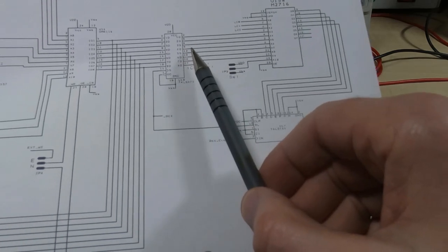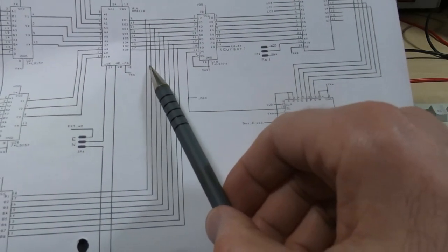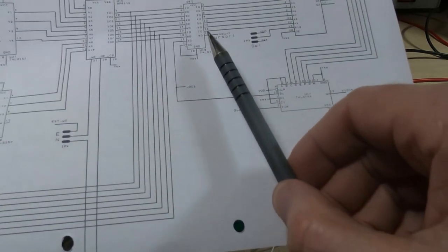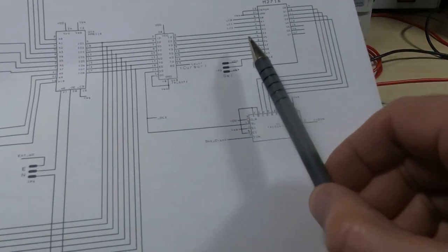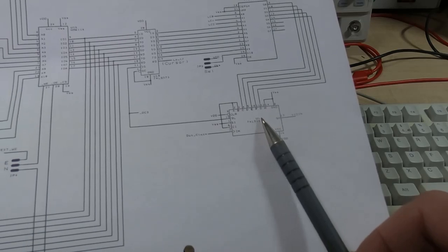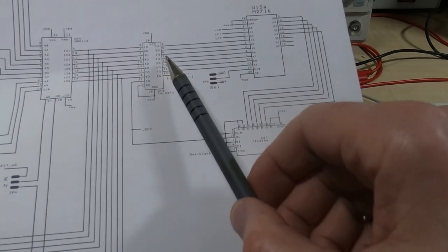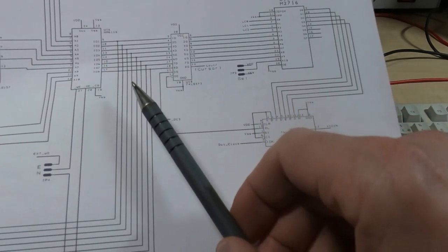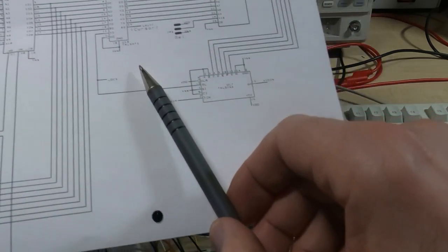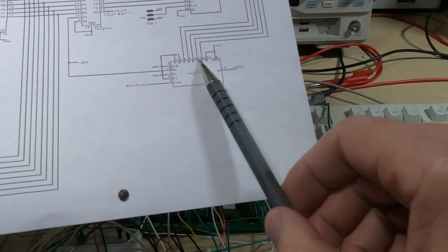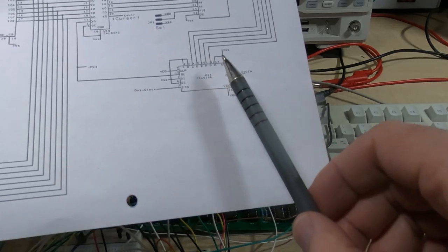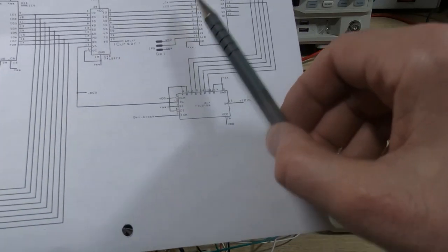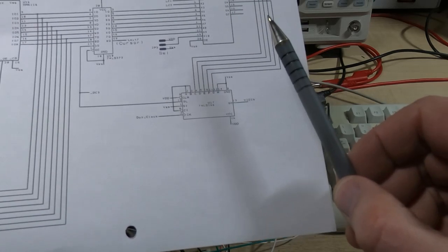We don't want it to keep changing, because if we decide to read or write data to the SRAM, and also as this cycles normally, this data will change, and we can't really have that part way through loading the shift register. But once we've loaded the latch, then we can do anything we want on this side of the SRAM data bus, and the data will continue to be correctly shifted out of the shift register, or loaded into the shift register, after the ROM has a chance to select the appropriate data.